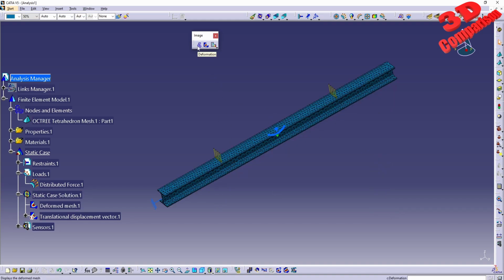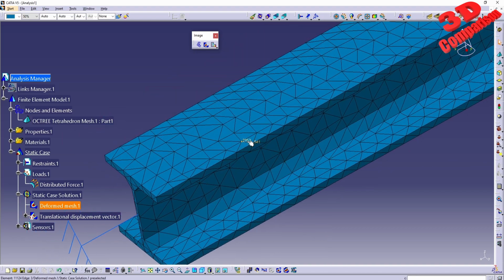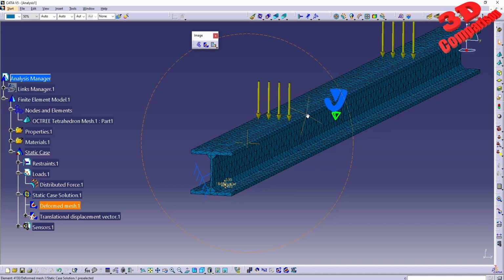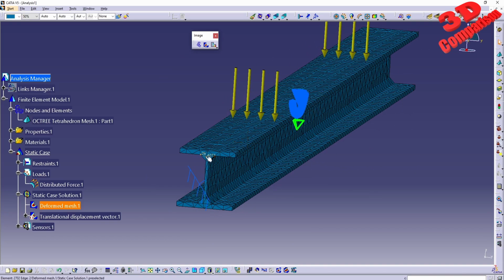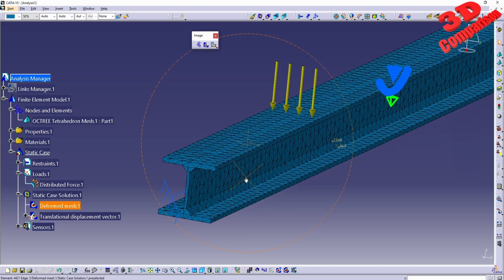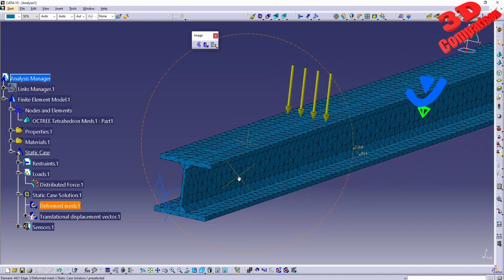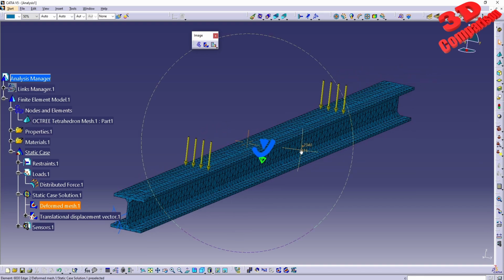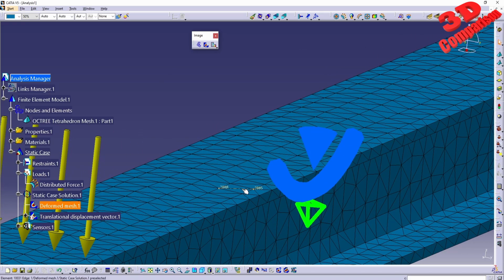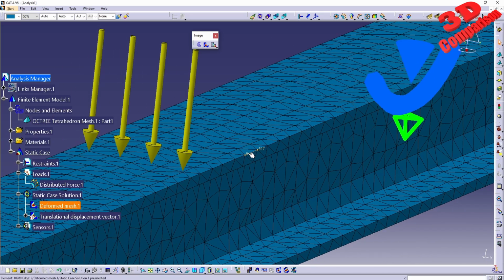But now, since the mesh used for this is much more refined, if I go over here on the deformation, you're going to see that this is more accurate to the shape of our final profile. We can even go further, since the computational power is not that high, and easily remesh into smaller elements. We see all of those elements now. If I move my mouse, they will be a lot smaller.